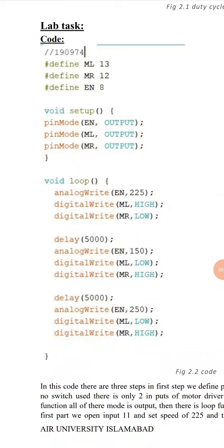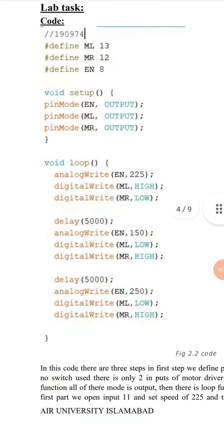Remember not to use the Arduino TX and RX pins in it, so that you could avoid any kind of error in your code, because usually Arduino IDE does not accept TX and RX pins, because they cause errors. They are basically the transmitting and receiving pins, so they are not used in the code.